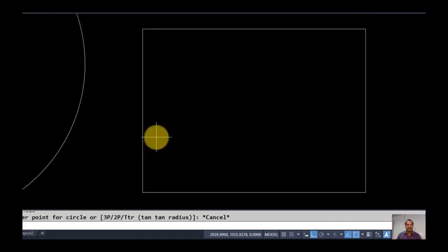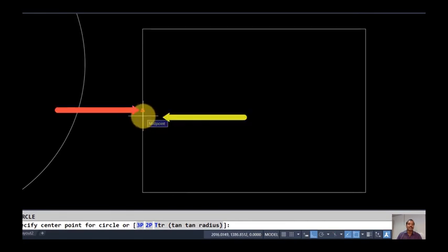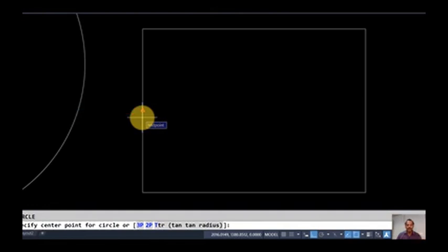I'm going to keep the center point exactly the mid of this line, right? Okay. I'm moving the mouse exactly near to the midpoint. See now, the distance of the points and my cursor, how much gap is it? It is very close, right? This is the range in which you are going to catch your object snap points. Now it is very close, right? Let it be. I mark the range now.